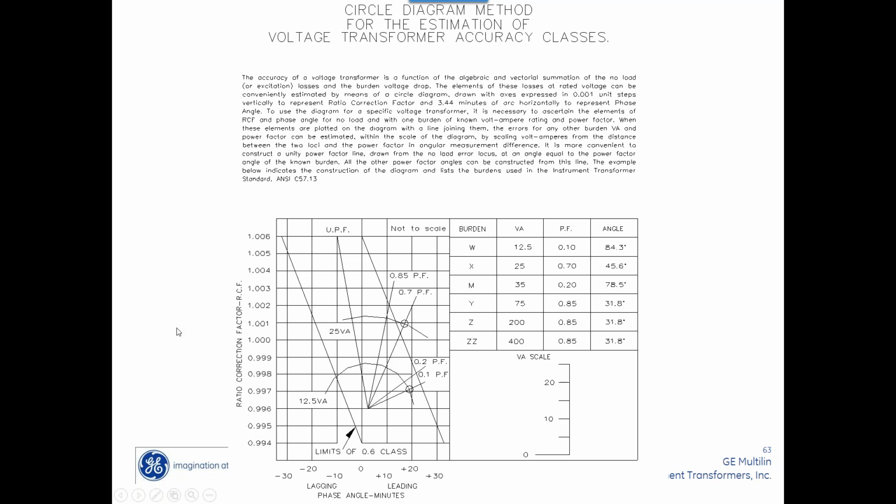Just like I had the parallelogram for the CTs, if somebody wants to know, here's the estimation of the accuracy for voltage transformers. And a lot of that depends on the power factor. So that's how that's set up. And here's the different burdens and how they're rated.